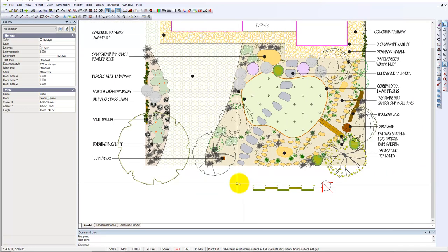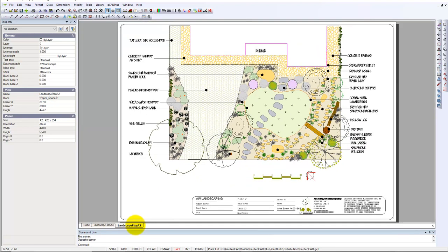So no matter how you print your drawing, if you always include a scale bar placed in model space within the view, any construction team worker who picks up the drawing, no matter what size it is, can in fact scale off if they need to. Of course, putting dimensions on is a much better way of helping your design team to work.